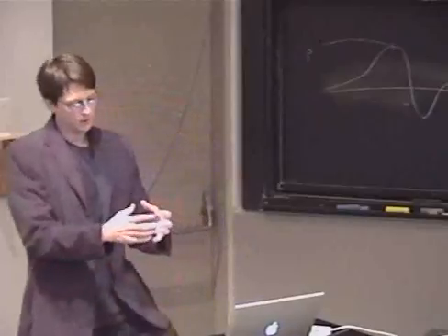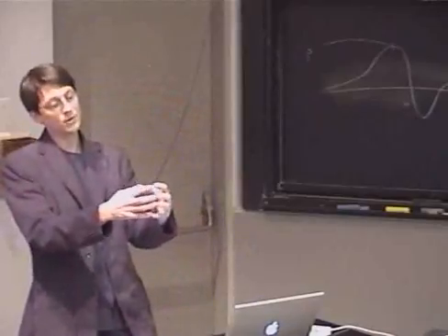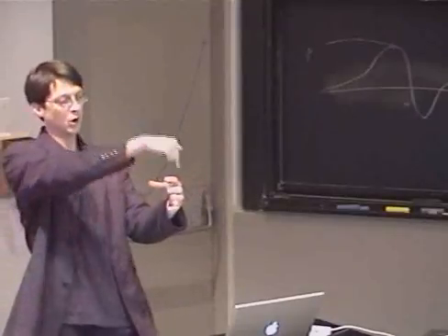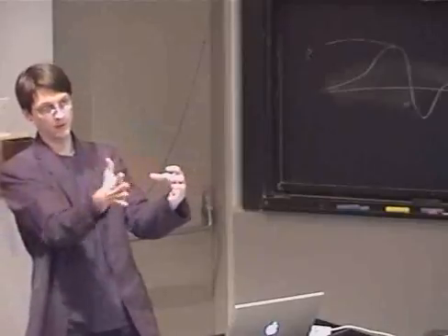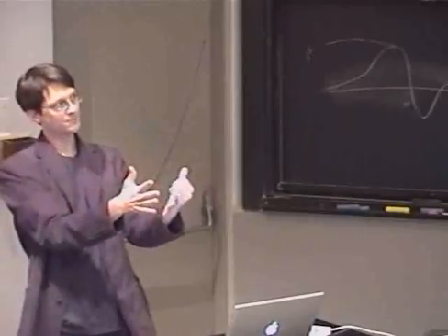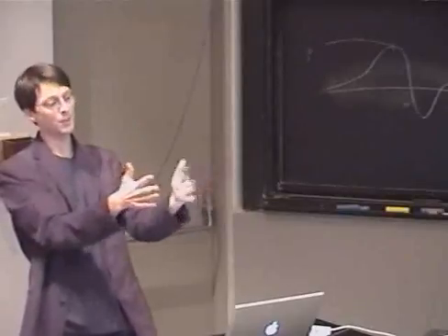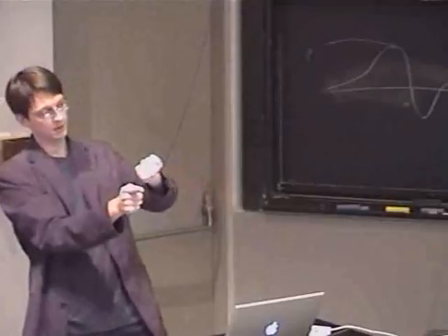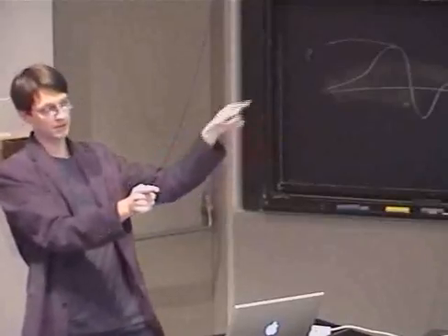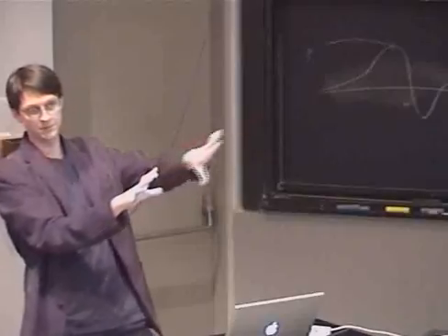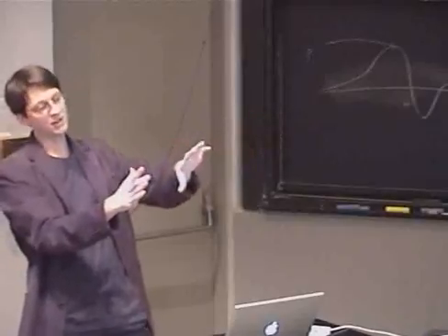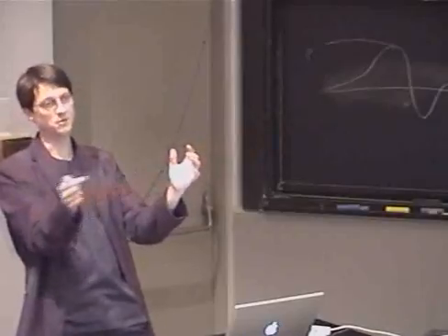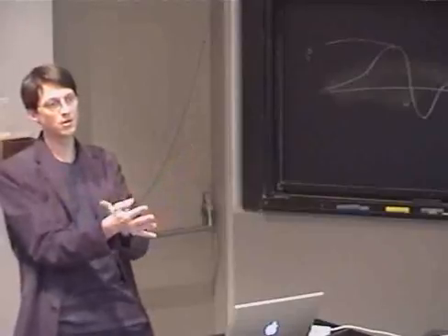Yeah, well, if you take a ball, and there weren't any drag, the flow would just go around, and there'd be some pressure from the incoming wind, and some pressure on the backside, so that there'd be no net force on the ball. But what happens in reality is that the flow separates, and you get sort of turbulence impact. Because of that, you have an asymmetric force on the ball, which is what's manifested as the drag. So it's a combination of all those factors.